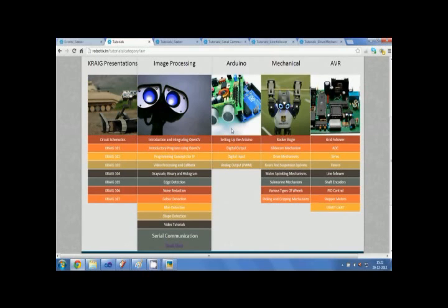For most video games, you must have seen that W makes the character move forward, A left, S backwards, and D right. And we can use Q for stopping. So similarly, if you burn your code such that if the character received is W, the motor drivers make the motors move forward in whatever orientation you've decided. Similarly, for A, it makes it move left, for S, backward, for D, right, and for Q, or any other character for that matter, it stops. Now, these are the 5 kinds of motion that a differential drive can do.